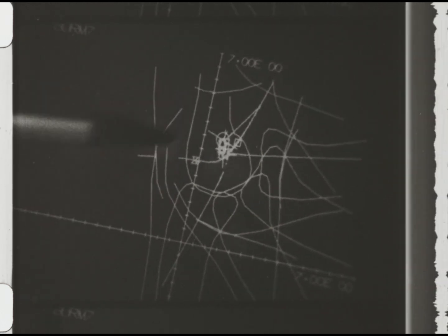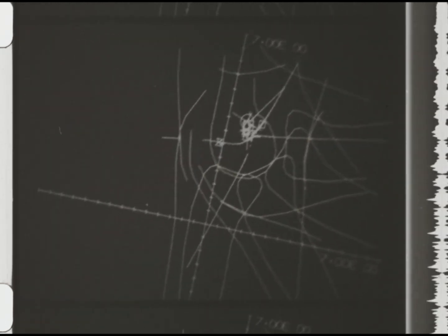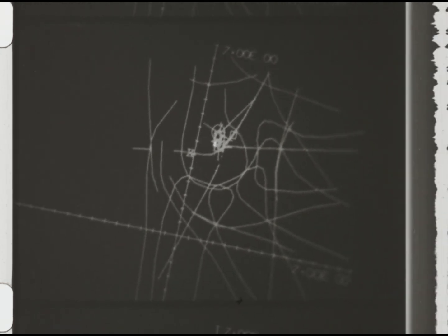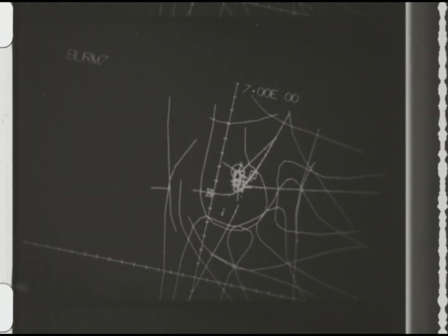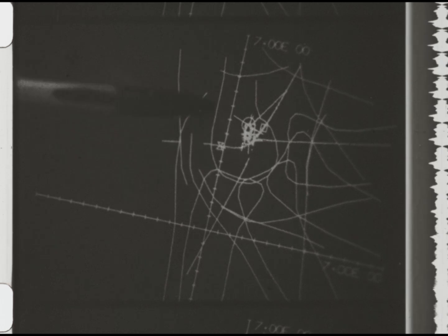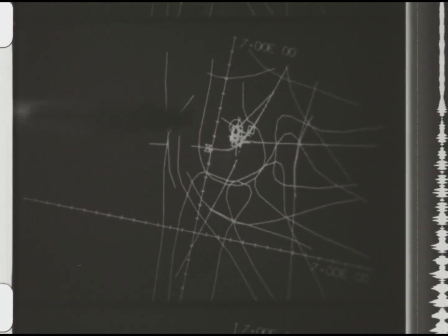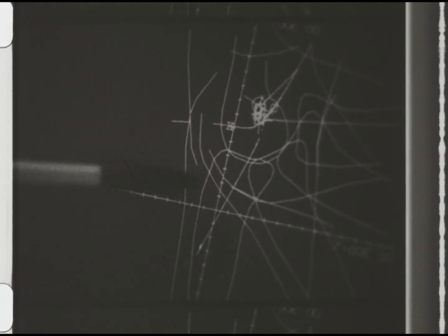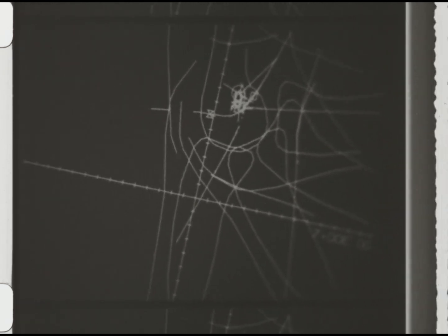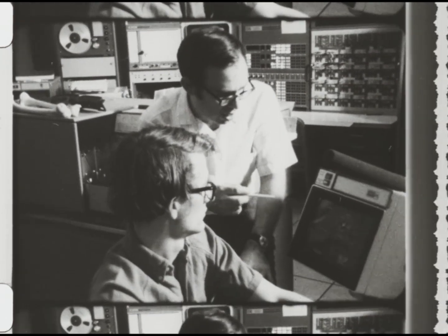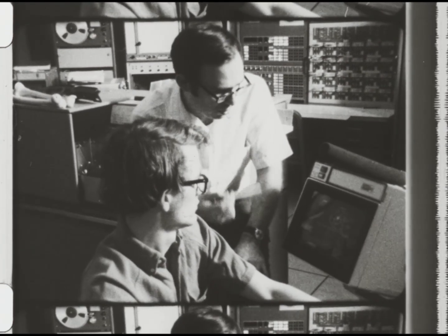Furthermore, now that the designer has selected his first link for the mechanism to guide this body, as he selects his second link, the computer is flashing on this table down here at the bottom of the screen. Right now, the computer is flashing double crank. This means that were the designer to select this particular link that is represented by this bouncing spot up here, he would end up with a double crank mechanism, a linkage in which both of the members that are pivoted to the framework will be capable of continuous rotation.